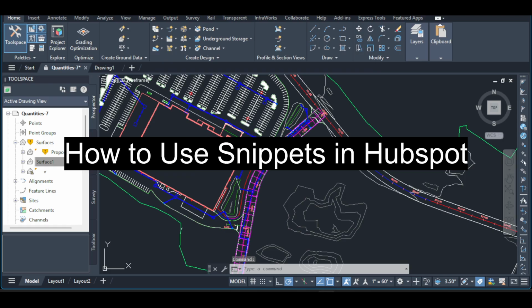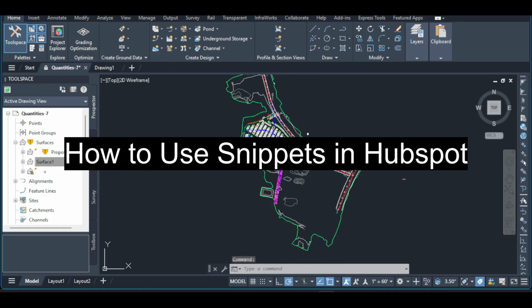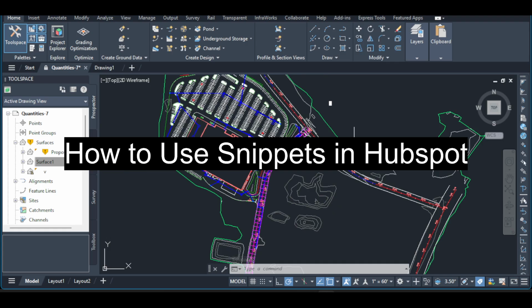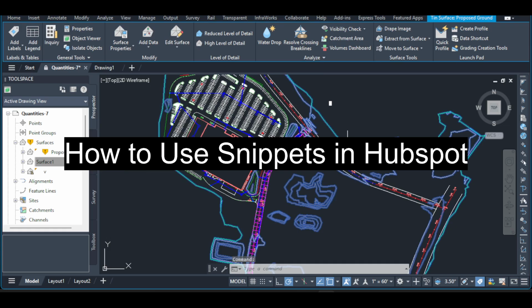Civil 3D will process the data and build the TIN automatically. Take a moment to look over the result in your drawing. If your surface style displays contours, you'll see lines that represent elevation changes. If not, you might see only the surface boundary, which is still fine for a quick check. Look for obvious issues like spikes, flats where there shouldn't be any, or triangles stretching across gaps.